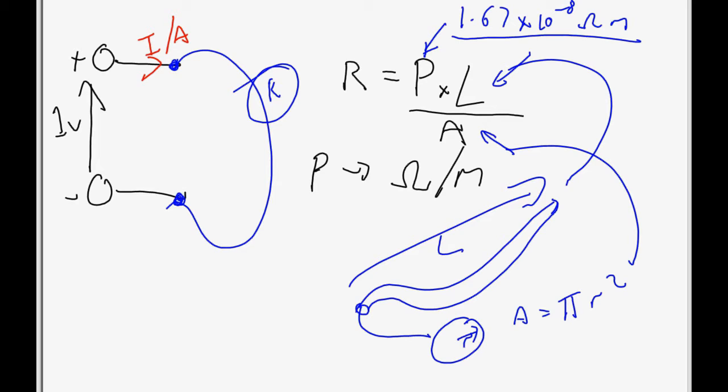It's not going to change too much, but it will change if there are any impurities in your wire, because I very much doubt that it's going to be a pure copper wire that you'll be using. And it's also going to vary with temperature. But for a ballpark figure, this value is perfectly fine. It's not really going to deviate that much unless you do something extremely drastic to the material, or the manufacturing process has gone completely wrong, or it's a cheap piece of material that you're using. But generally that figure is quite straightforward.